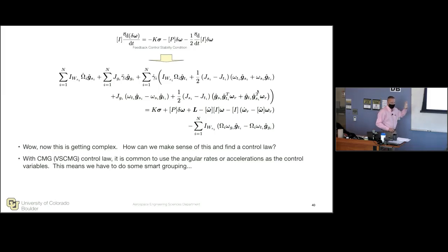Many variable speed CMG papers always talk about you're spinning at 5,000, 8,000, 10,000 RPM nominally, and then you vary a little bit around it. But if you reconfigure, and you'll see with the null space motions, we change wheel speeds quite a bit sometimes. It would be interesting actually to see what happens, because as the wheel speeds go through 0, what happens to my CMG mode? If big omega becomes 0, and you gimbal something that's not spinning, you're not going to get any gyroscopics. So all of a sudden you lose one of these big things that you think is going to give you torque. Fortunately, we still have this, right? So we will still have controllability.